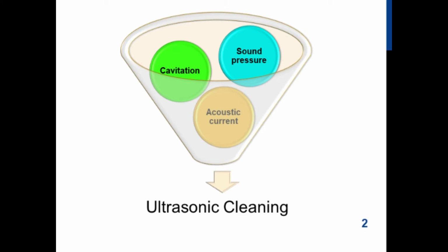Purification occurs due to the combined action of various nonlinear effects that occur in the liquid under the action of powerful ultrasonic vibration. These effects are cavitation, acoustic currents, and sound pressure. The main physical phenomenon that provides ultrasonic cleaning is ultrasonic cavitation, the implosion of bubbles that occur under the action of changes in fluid pressure during sonication. This is the release of energy which separates the dirt from the body.